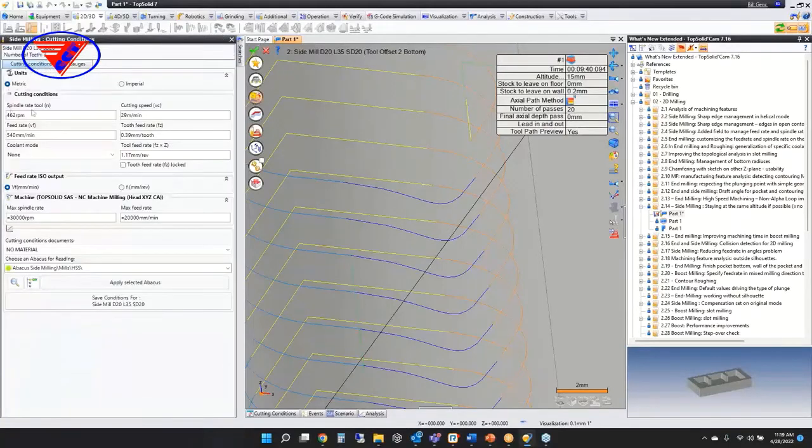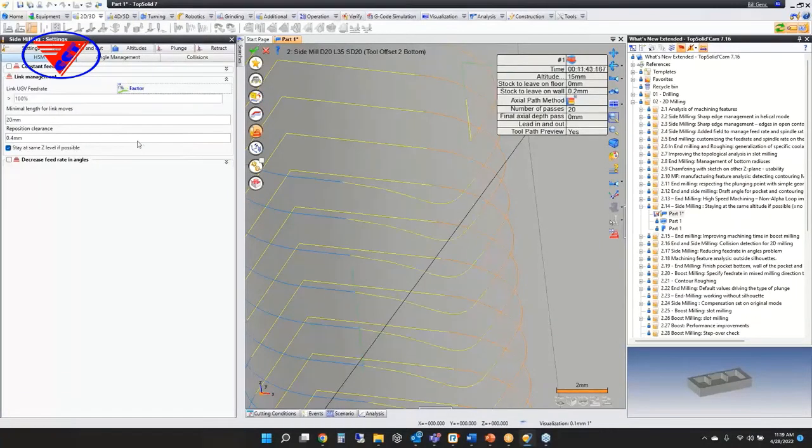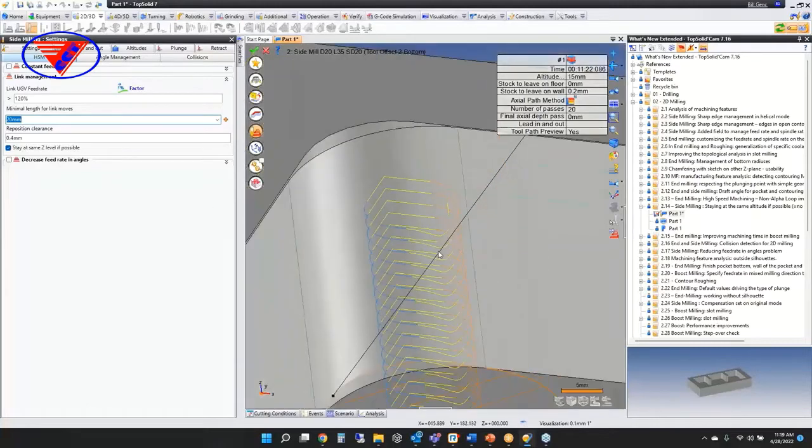Let's go look. My main feed rate is 540 millimeters a minute, okay? So maybe in here, I want to set a factor, all right, and we'll say 120%. Just 20% faster, okay? But at the end of the day, you now have extremely nice control over movement like this. Now, where this does not work is in helicoidal, but in helicoidal, you're going to get your complete profiles anyway, okay?